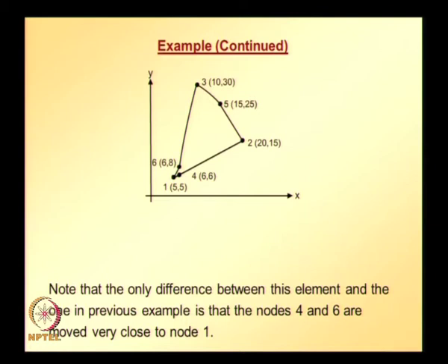We learnt earlier that the interior nodes should satisfy the condition that they should lie between L over 4 and 3L over 4. So, once that condition is violated, that reflects in the mapping. That is what we are going to observe in this example.